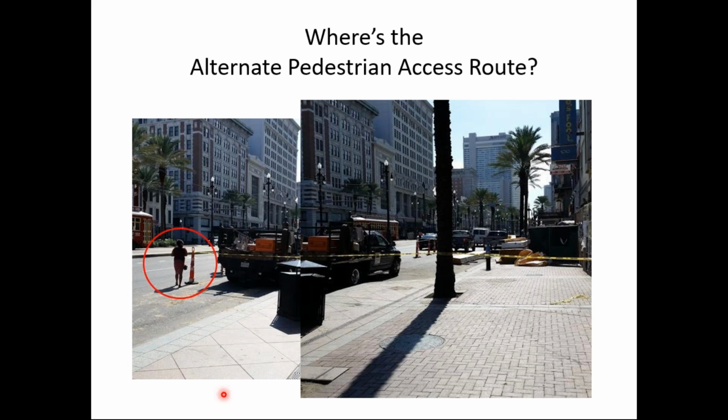area. I was there for a conference a year or so ago and was just walking one morning before the conference started, and I came across this work area, which is not really a road or street project, as it looked to me. It's some sort of building reconstruction project. But notice how they had closed the sidewalk here with just this yellow caution tape, which of course is not detectable by a blind pedestrian using the long cane, as it's called, or the white cane.